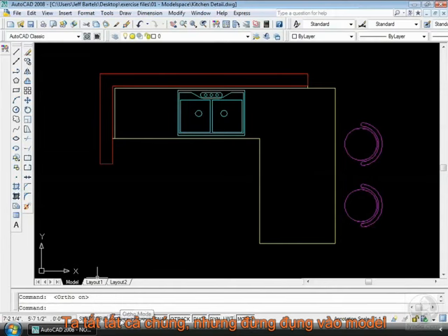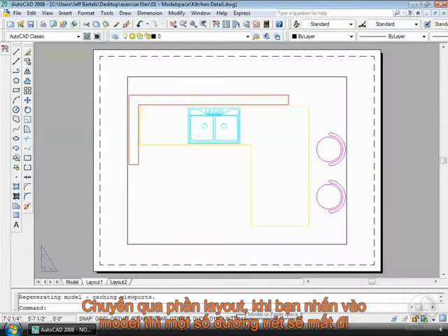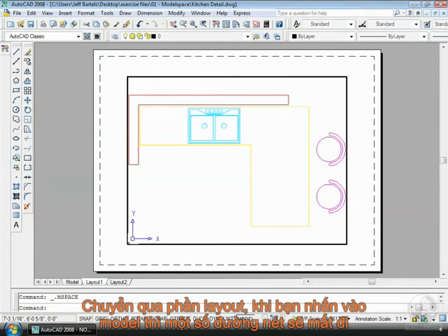Now, what I'd like you to do right now, I'm going to go through and turn all of my modes off. Once again, as we get to these, we'll talk about them fully, but for right now, I'm going to pop all of these buttons up with the exception of model. Be careful of model. I'm going to show you why. Let me click on model. That could be scary if you're just using the program. Hey, my screen looks different. What this actually did was pop us out onto a layout tab. And if you think you're going to return by clicking on this again, unfortunately, you don't. So be careful of that one.